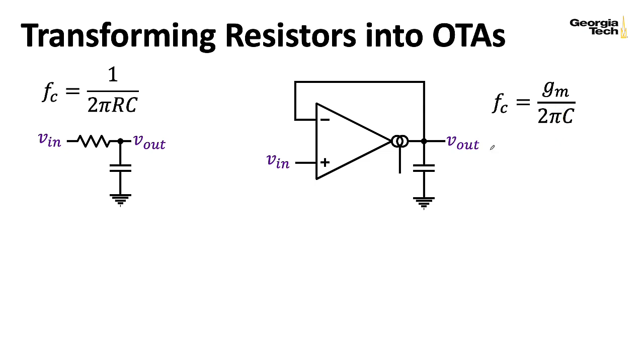And what is the gain of the OTA? Well, that's approximately 19.2 times I_ABC, which is the current flowing into the control pin input. So, as I increase the current flowing into the control pin, I increase the cutoff frequency of the filter, and as I decrease that current, I'll decrease the cutoff frequency of the filter.